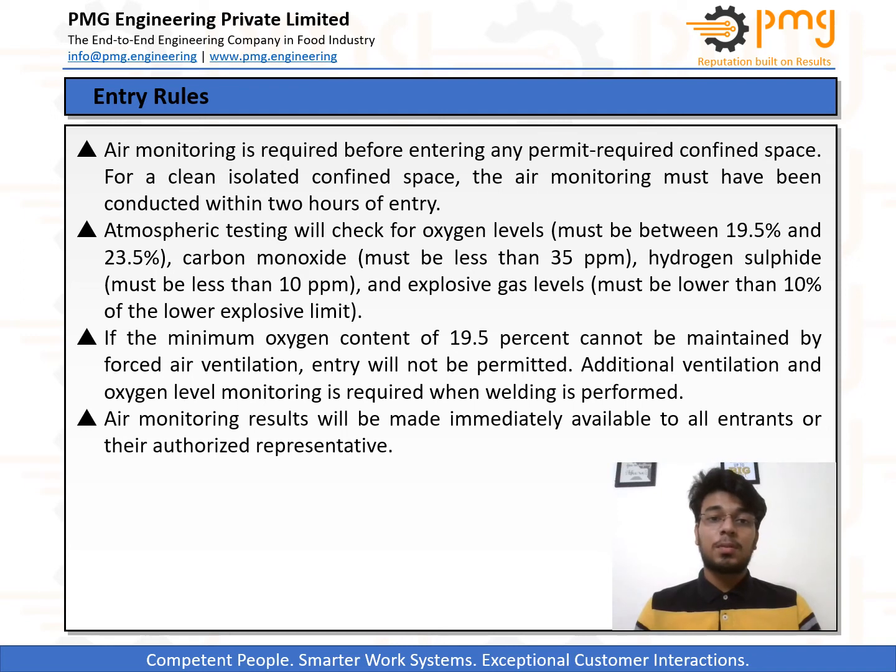Continuing with the entry rules, it is also very important to monitor the air quality of the area. So if the space is a permit-required space, monitoring should start 2 hours before. On the other hand, in the case of a non-permit required space, monitoring can start from 50 minutes, so it's a bit lenient in this case.